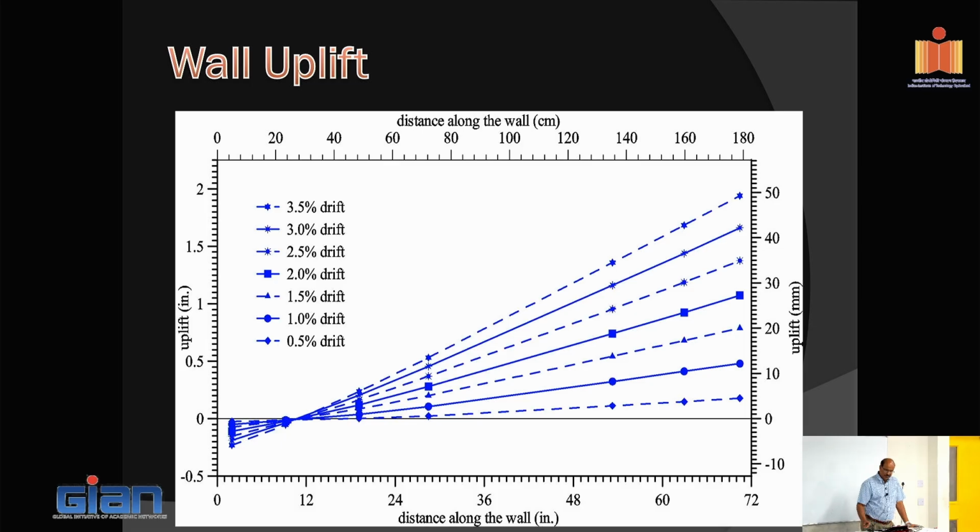What is the relative benefit of this horizontal post-tensioning in the frames versus a vertical post-tensioning in the wall? No, they behave in the same manner. The rocking in a beam, the bays are smaller relatively, right? So the gap opens up quite a bit. You had to account for it.